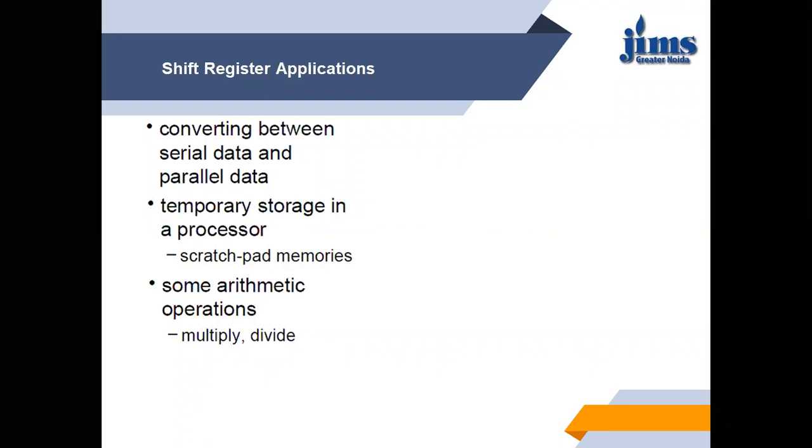Similarly, in case of division, when we are dividing a number by another number, for each next division you have to shift to the right side. Again, this shifting is done with the help of the shift register. On paper with pen, you can simply shift by one bit, but in case of the computer, when you are doing the process digitally, you need shift registers for the purpose of multiplication and division, where you need to shift a digit.